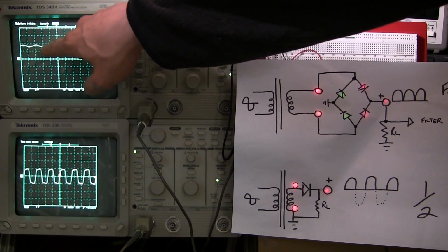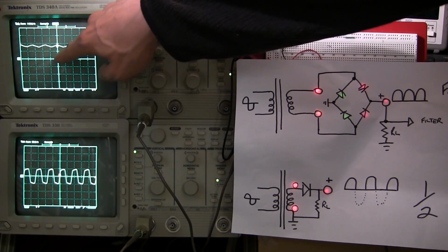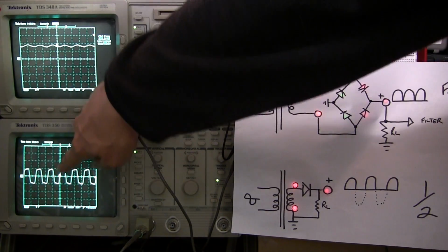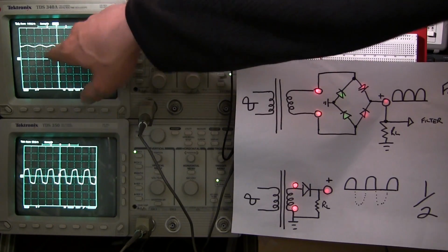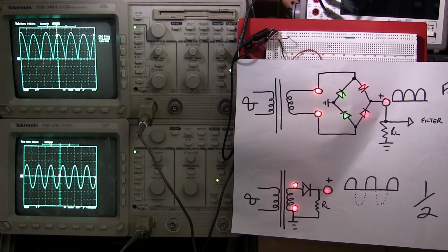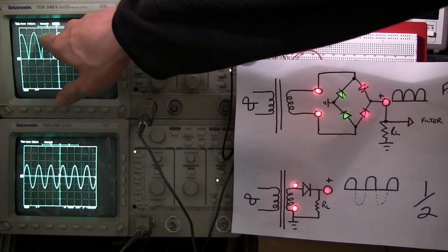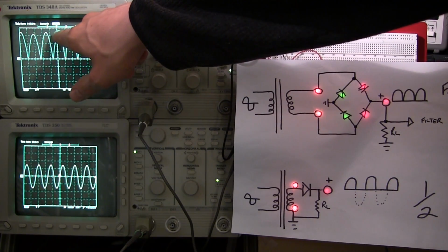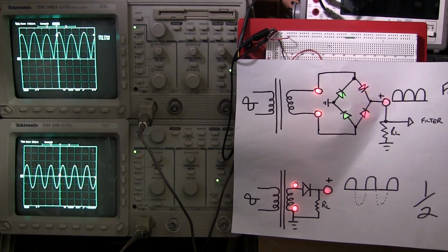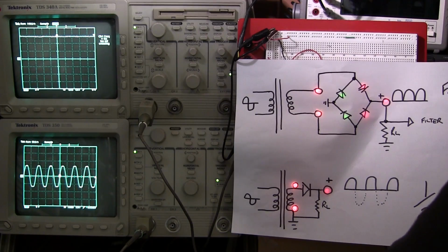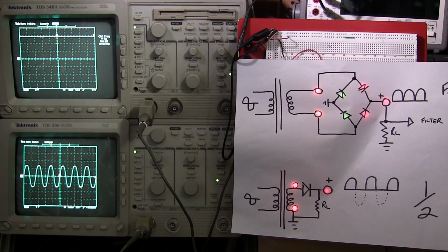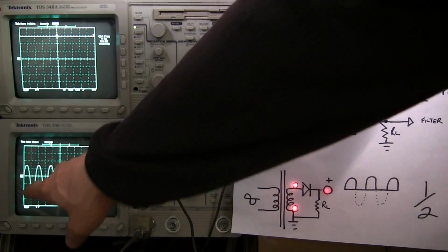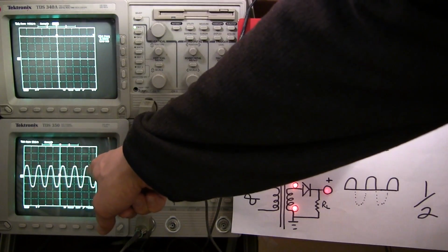So again, that capacitor is discharging and it's being charged up again and discharging in this particular area here, in the small area that's in between the peaks. So in between here, it's discharging, and then it's charging back up again with the next cycle and discharging, and so on and so forth. So if I add a lot of capacitance here, you can see that we pretty much get smooth DC, and that's with 1000 microfarad. So that's what the capacitor does, really. It's just holding it up here, kind of like a peak detection circuit.